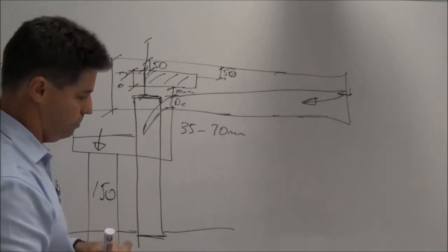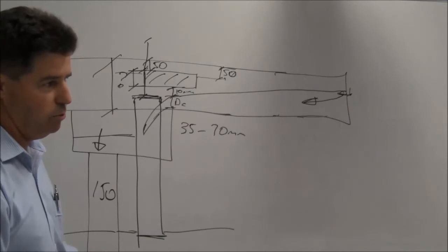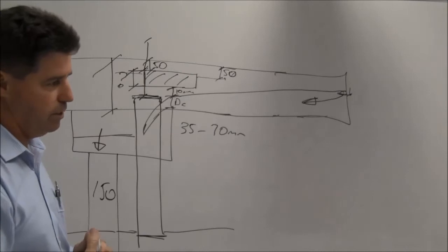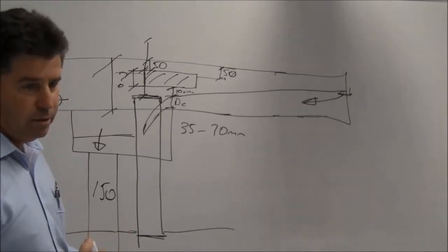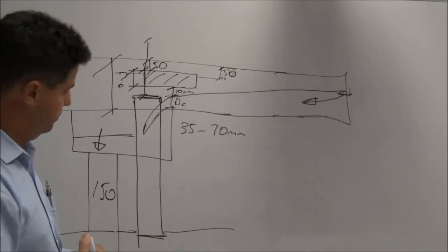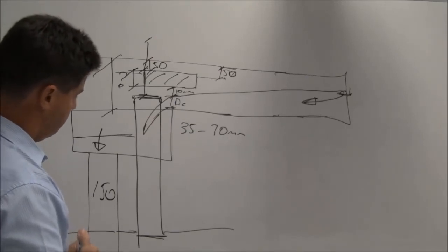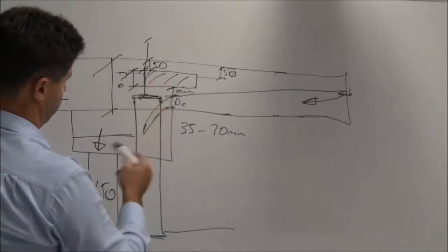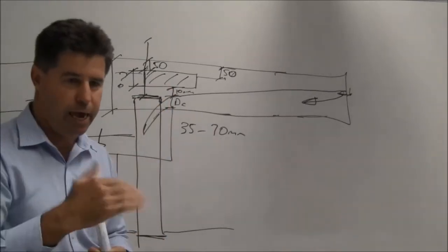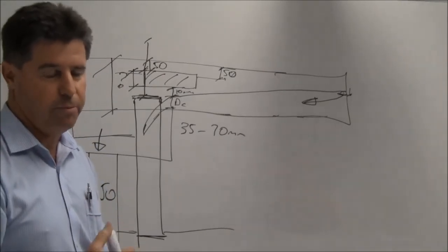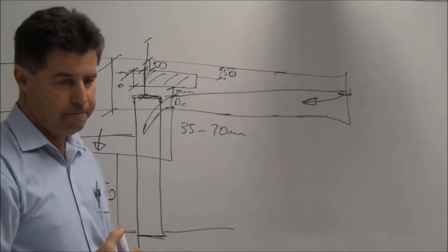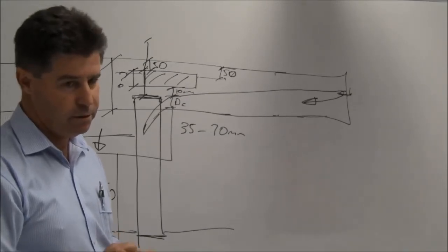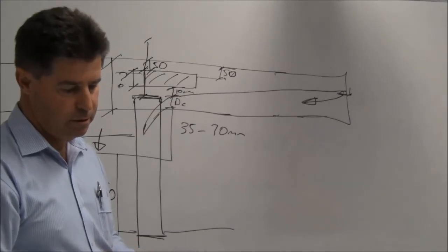Well, the 10 is just to make sure the water doesn't overflow when it's working normally. You can use whatever you like, it can be 20 or 30. It makes no difference. So you've got critical depth, in this case 35, plus the 10, 45, plus the 50, plus the 50 freeboard. Your head of water might be more, might be 80 mil, that you need to add to the top to make sure it's going to operate the same way. Yeah, because I got 195. Make sense? I think mine was 60 or 70 or something.